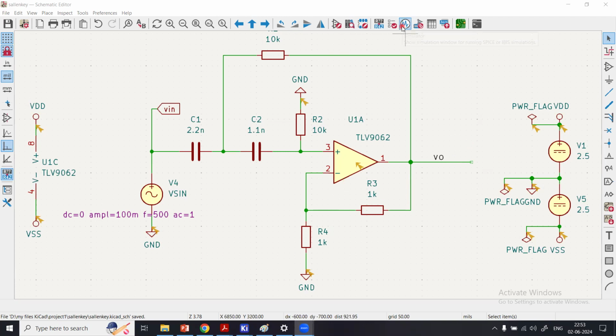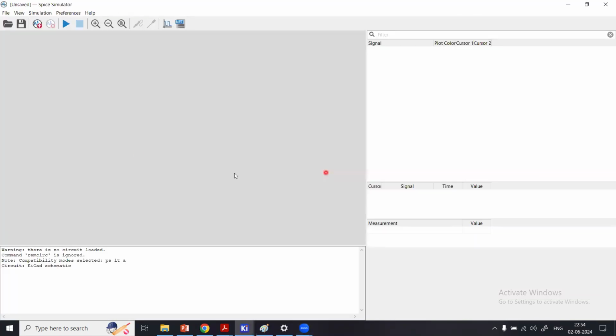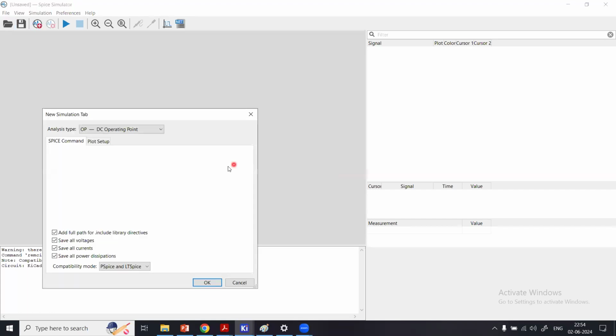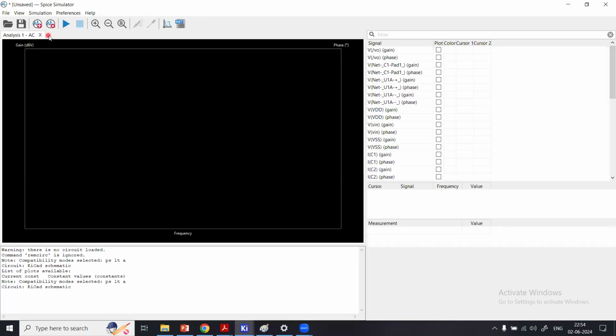So what I'll do, I will just hit the simulator button. I will then click here new analysis, and then I will choose DC operating point. That is just giving me the voltages and the currents in the circuit. Rather, I would skip that because we have done that in a previous module. So I will click small signal analysis. I will say take 2000 points, start frequency 1 hertz, stop frequency, let's say 100 megahertz. Okay, 100 e to the power 6. Click OK.